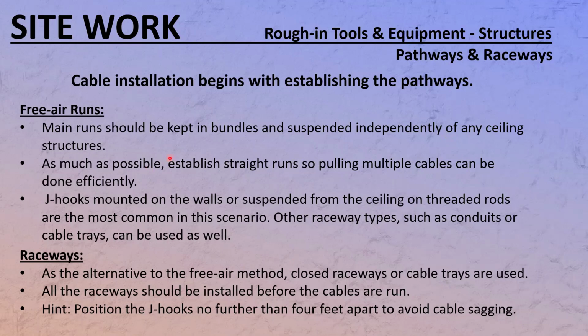As much as possible, establish straight runs, so pulling multiple cables can be done efficiently. If you establish a straight line, you can easily pull a greater bundle of wires in a straight line. So if you're going to have 30 wires going from that place to that place, somewhere at the end of that pull they fan out and go in different directions.